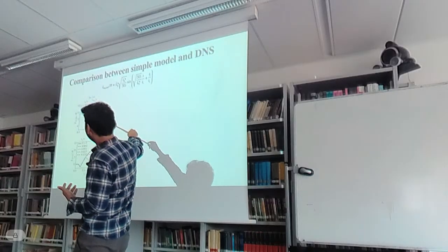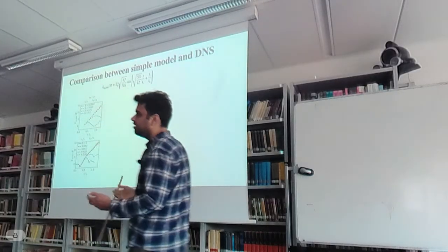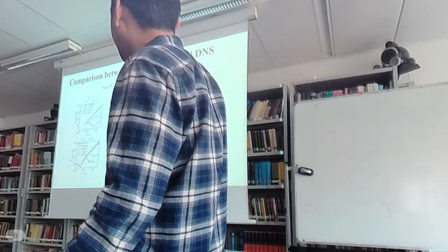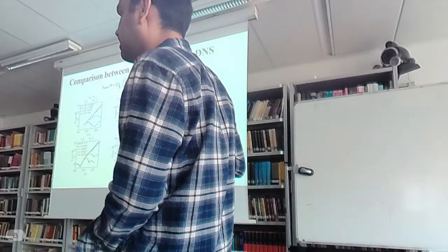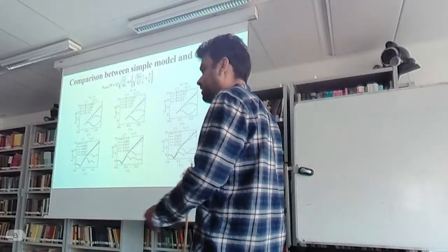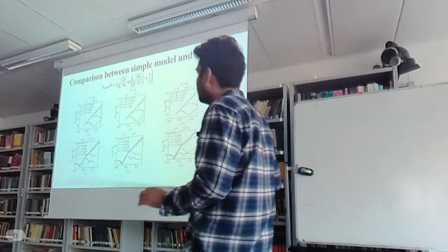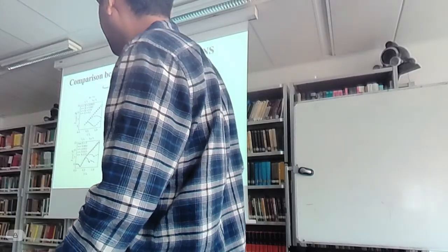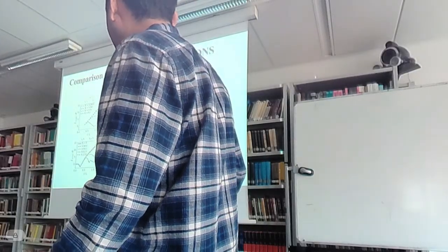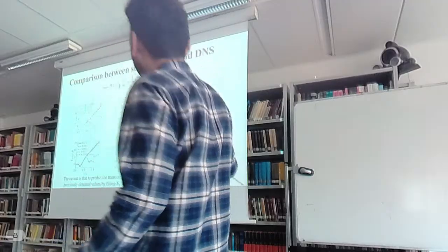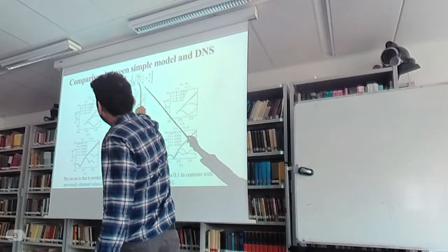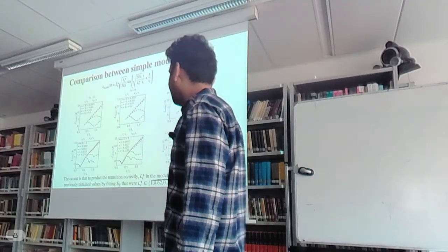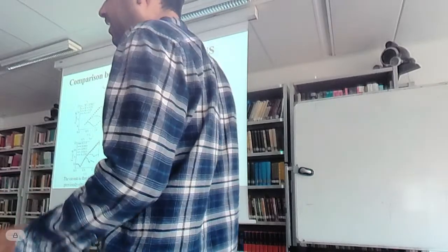So when this time is comparable to the breakup time, you have this jet retracting back into the nozzle. So with this kind of model, you can predict when you transition from jetting to no jetting but a retraction phase. The model, like I say, different Deborah, but it's for infinite Deborah, so it's the same for all of these cases. But there's one problem with this, because there I again have to fit this LE equal to 0.1 as compared to the previous values that I obtained by just fitting the elastic energy.